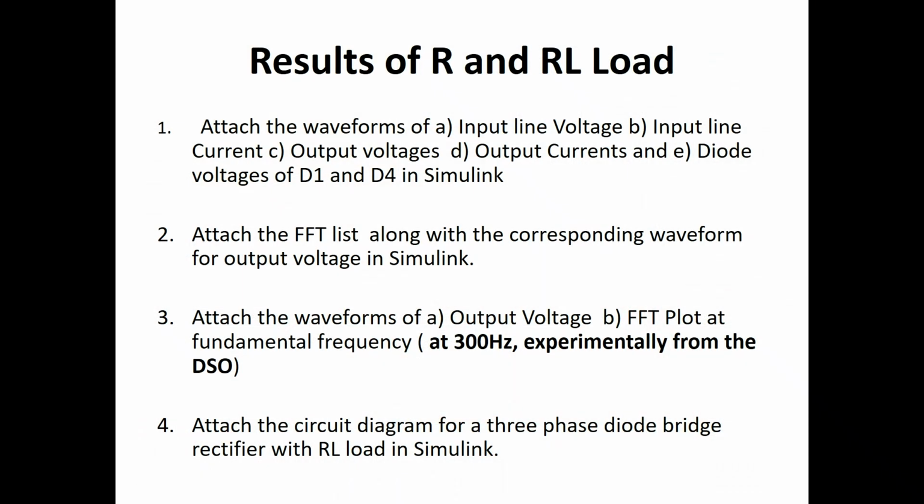Results of R and RL load: attach waveforms of input voltage, input line current, output voltages, output currents, and diode voltage of D1 and D4 in Simulink. Attach FFT list along with corresponding waveform for output voltage in Simulink. Attach waveform of output voltage FFT plot of fundamental frequency at 300 Hz experimentally from DSO. Attach the circuit diagram of three-phase diode bridge rectifier with R load in Simulink.